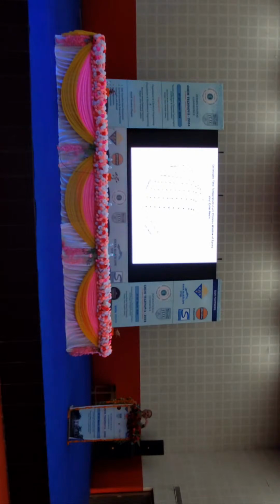Obviously we may obtain the kinetic parameters for higher temperatures, say 50 degree, 60 degree, 70 degree. I have only data on how the resin cures at the studied temperatures, right? But with the curing kinetics parameters, I can extrapolate to lower temperatures as well as higher temperatures, so that the complete cure profile of the resin can be obtained, like the time, temperature, cure process window. For that, I have to extrapolate the kinetic parameters. That's it. So next one, please.